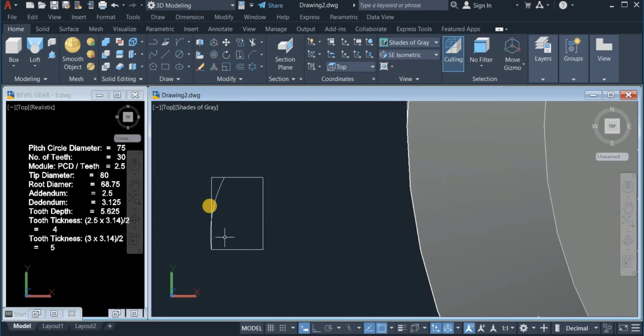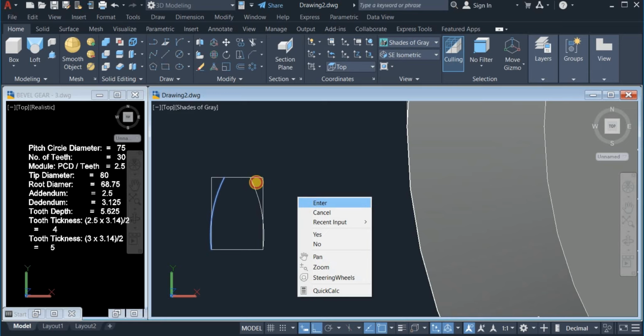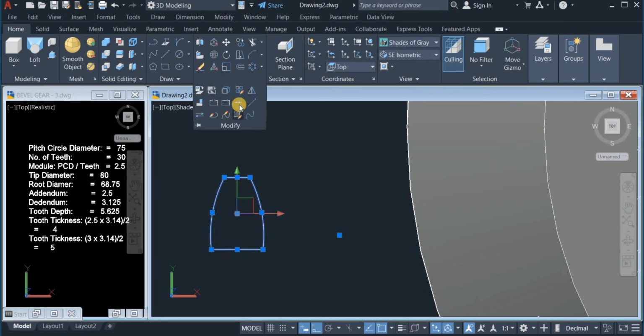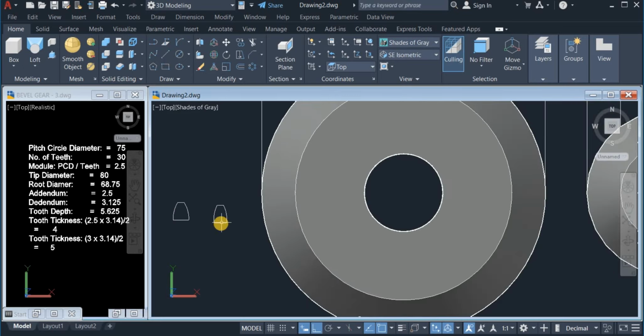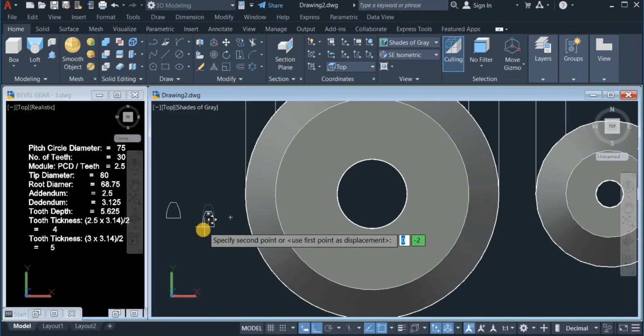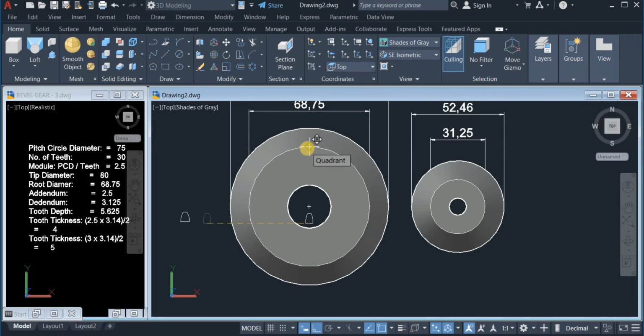Should be alright. Now use the mirror command again. The midpoint. Check this. Okay. Now remove this and close up the geometry again. Okay, now use the join command. Join them up. Okay, so these are the two profiles for this very big one. So move this small one. Move this from this point. Drop it at the quadrant point of this one.